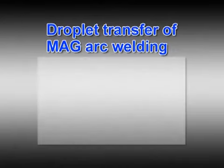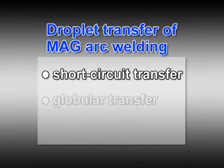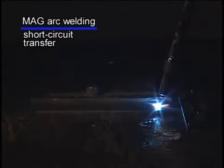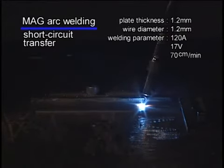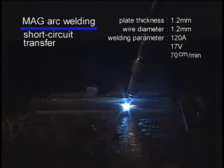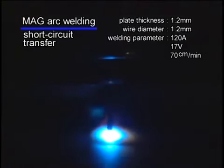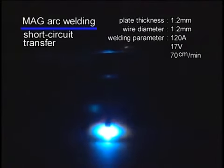In the MAG welding process, melted metal particle transfer is divided into three types: short circuit, globular, and spray transfer. First, we will observe short circuit transfer. This example shows a 1.2 mm thick plate using the MAG welding process. The welding parameters are 120 amps, 17 volts, and a travel speed of 70 centimeters per minute, with a 1.2 mm diameter welding wire.